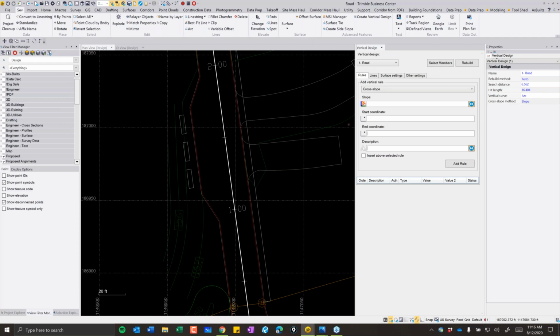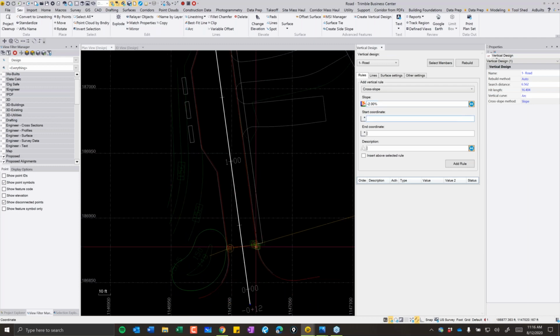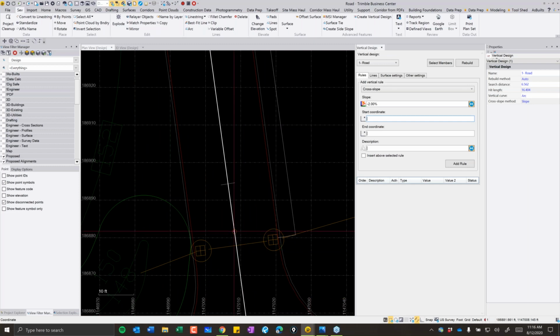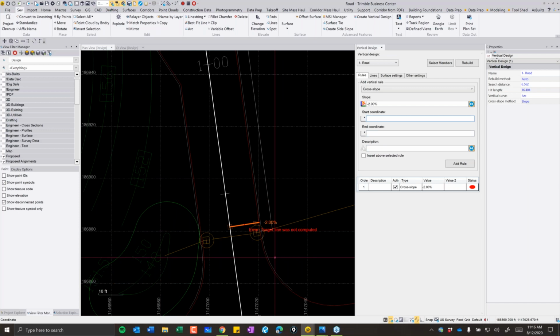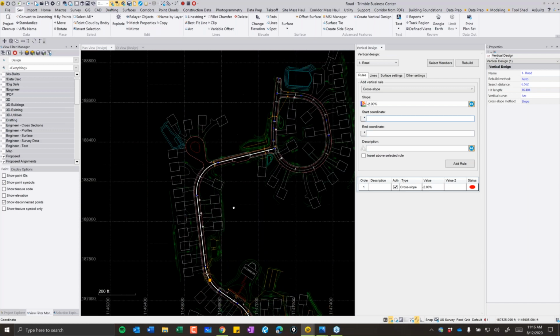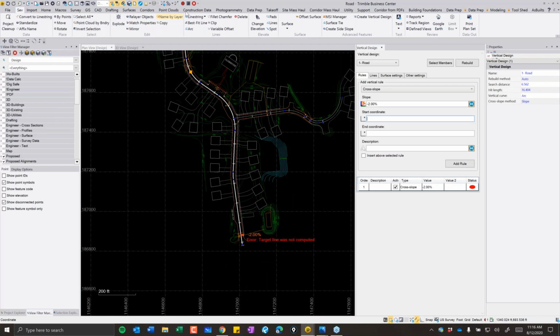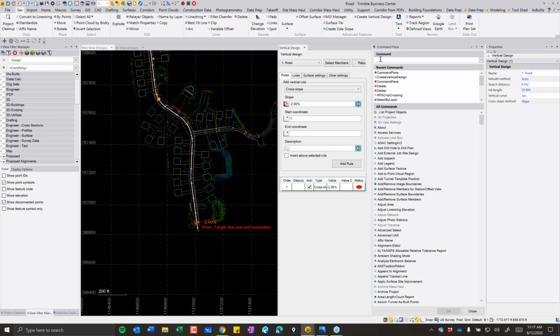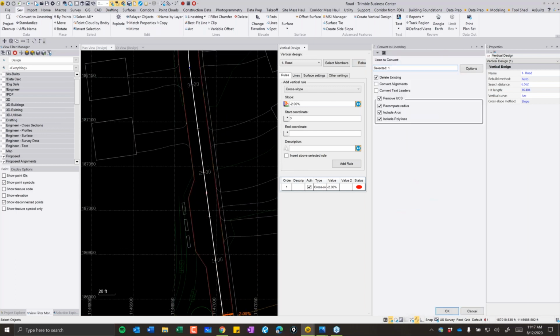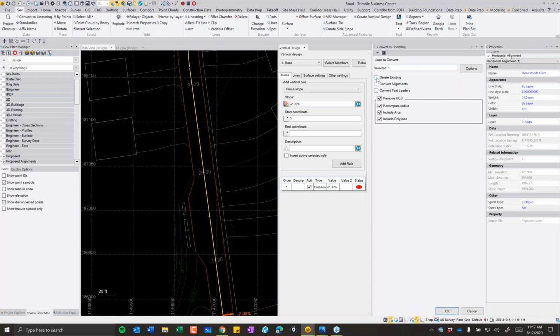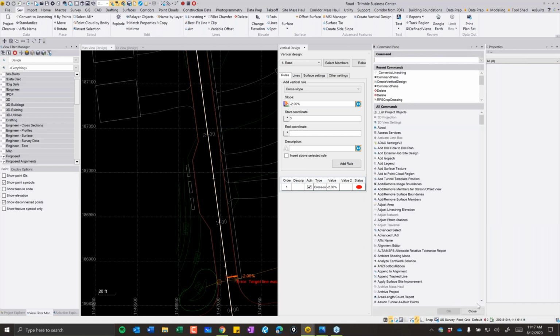Okay, let's show us what you do. All right. So right now, and this is something that you could do with the corridor instruction, I much preferred using the vertical design though, because again, now you get your 3D line work. Now this is probably a bug because the vertical design doesn't always like alignments, which is something to keep in mind and not to get deterred from, but you can use the convert to convert an alignment to a line string, and it works just the same.